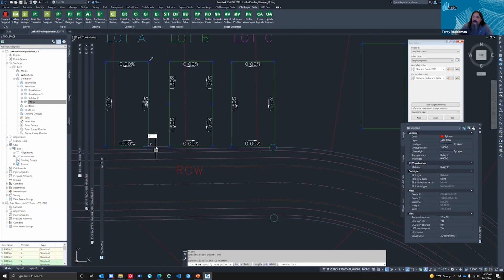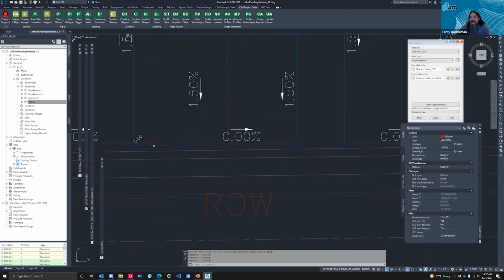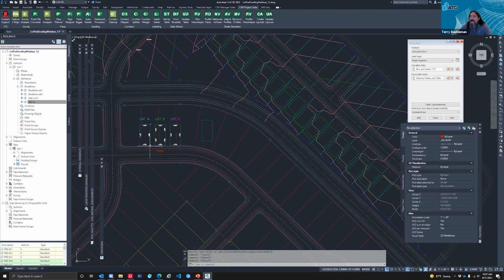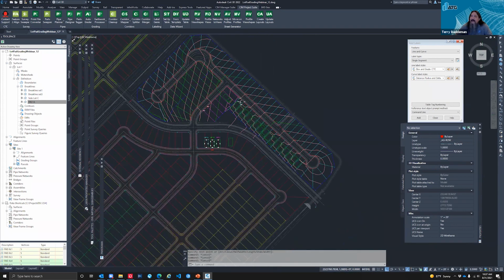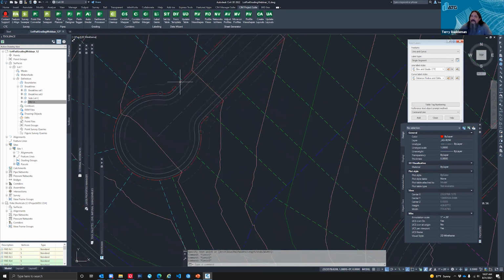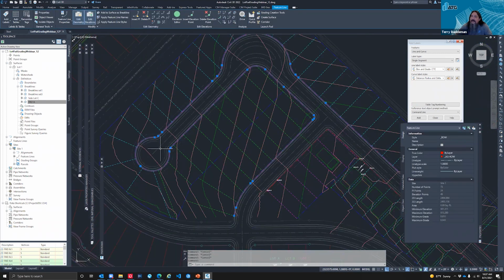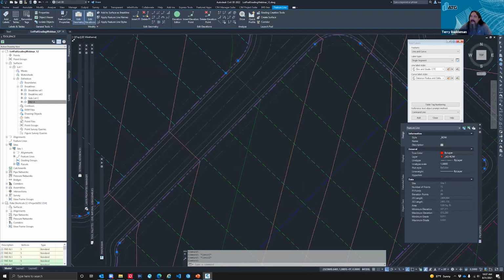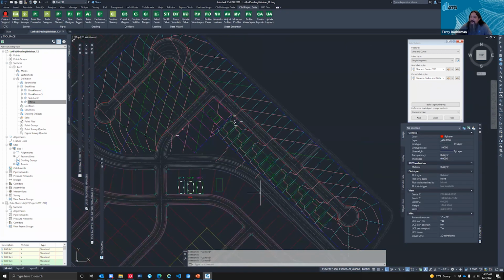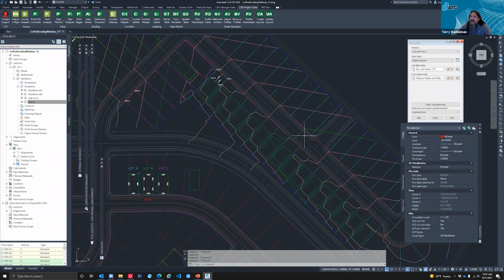I'm going to put an offset of just 6 feet just to center my lot. So what this means is that this is going to be my base point of my template when it places it, which means it's going to use this range for each one of these intersections to place the template. And I'm going to place it around this corner as well, and we'll end it over here. I can break it, but let's just see if we can use a range as well. So with that, let's go ahead and create a new grading family and apply this template.